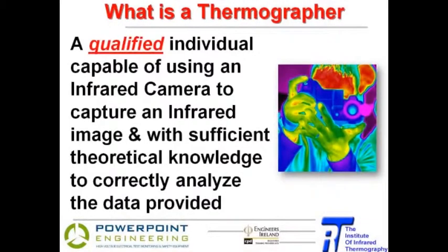So we say, well, what's a thermographer? A thermographer is a qualified individual, somebody who is capable of using that equipment, firstly to capture the image, but then with sufficient theoretical knowledge to analyse the data that's contained in that image. There'll be elements of image manipulation that may have to be taken into account, accounting for the differing emissivities of materials, which we'll look at further on.